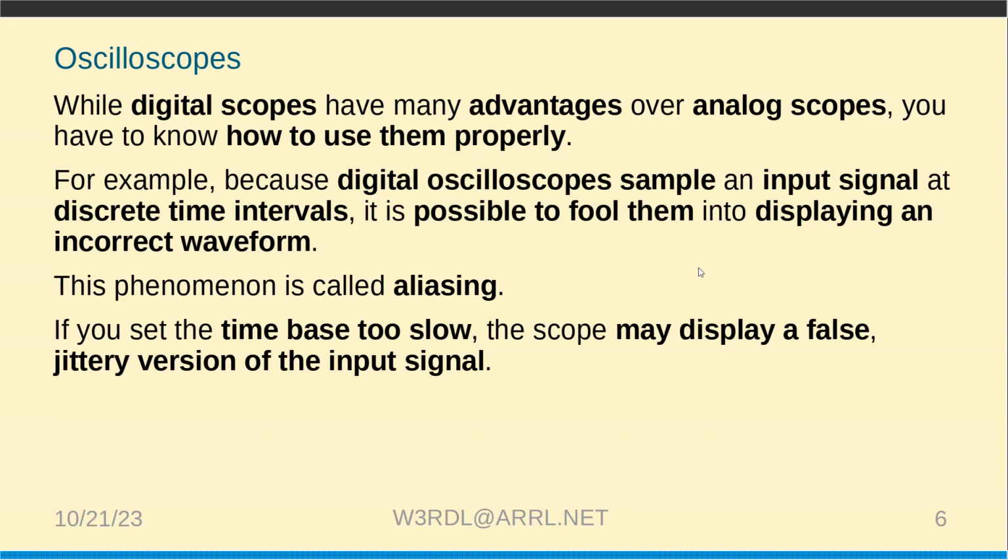If you lowered the sample rate, you ran out of memory. Maybe at the high, if you had the high sample rate, yes. Because you only have so much space to put it. If you're doing 1 million samples per second and you're doing a 3-second sweep, you're going to end up with only part of the screen, or it has to reduce the sampling rate. Oh, yeah. But today, storing 3 million samples is a piece of cake. 2 gigabytes, 5 gigabytes are now terabytes.